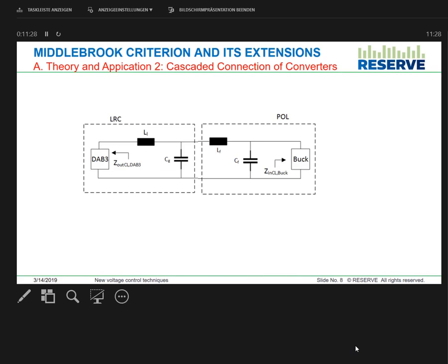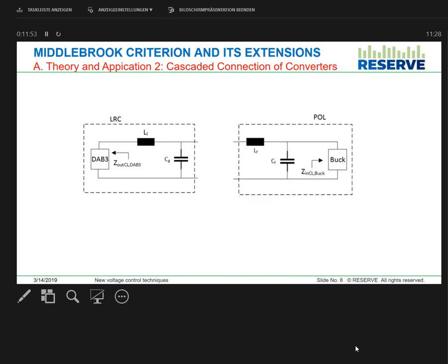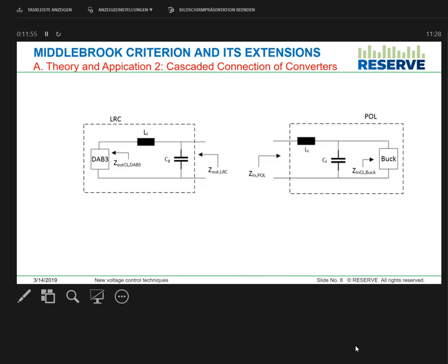So similarly, for a load side converter you might add some input filter later in order to control the harmonic current drawn from the grid. For example, in this case, let's say this node is the grid. In that case, you first have to model the local impedance of the converter. Then you try to split it up and model the entire impedance as seen from here. And you can repeat. So this is the idea for checking the stability of the interconnection.